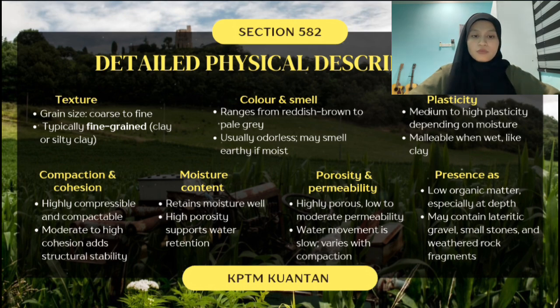Next, porosity and permeability. The soil is highly porous but has low to moderate permeability. This means water moves slowly through it, though permeability may increase if the soil is loosely packed.